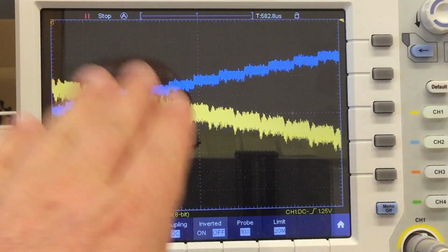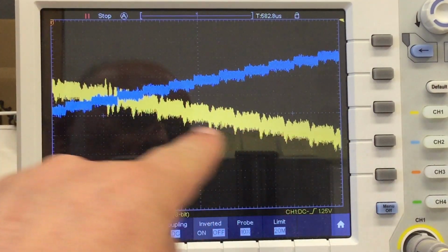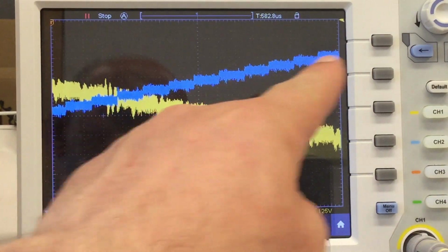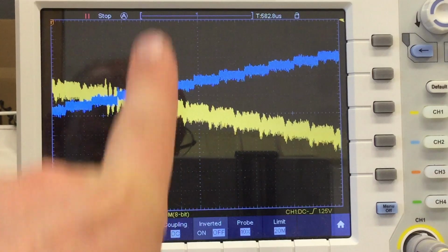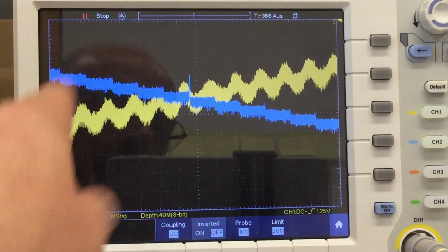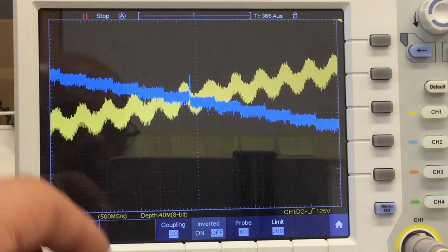So 0.01 microfarad or 10 nanofarad looks not as bad, but our unfiltered output is still better. So let's try getting bigger, 1 microfarad. Nah, things get definitely worse with a 1 microfarad output capacitor.